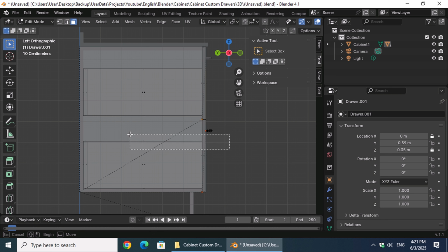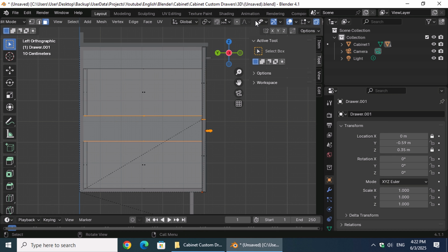Carefully hold down the left mouse button and drag to select the top edge of the inner bottom drawer, avoiding the dots in the middle of the other faces. Continue dragging to include the handle. Once you have selected the bottom edge of the upper drawer, release the mouse button to complete the selection. By scrolling the mouse wheel over the Tools panel, we deselect the X-ray toggle button.